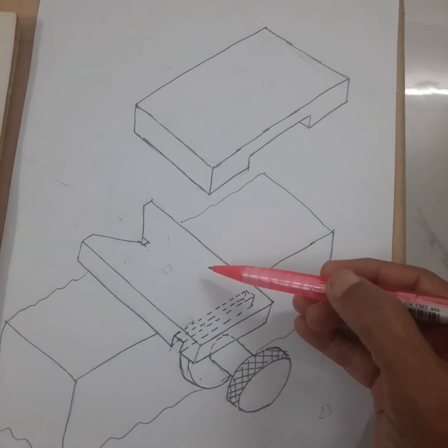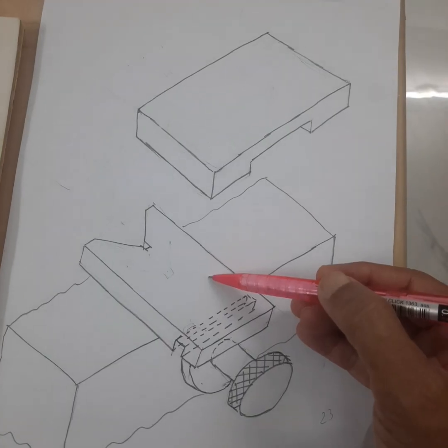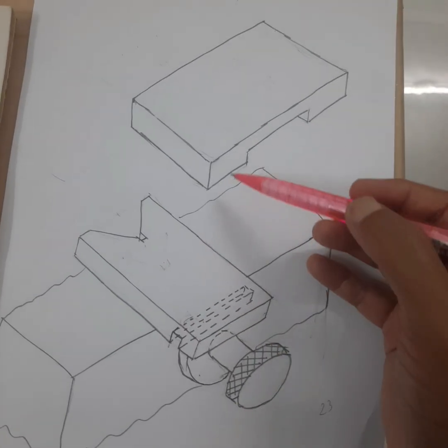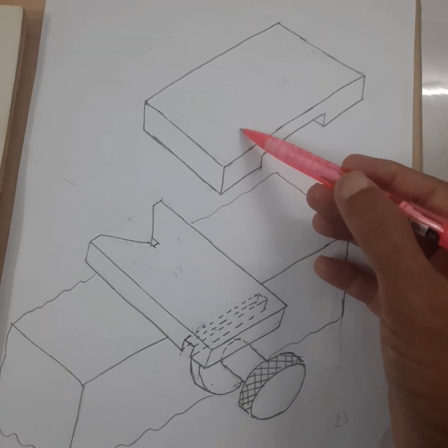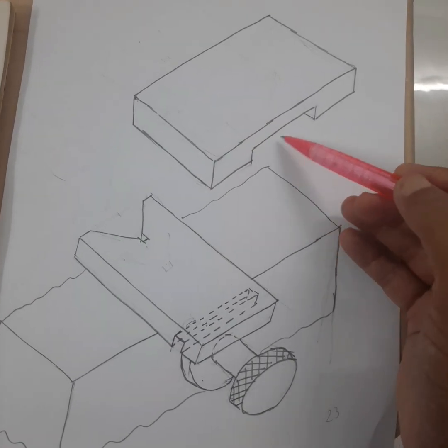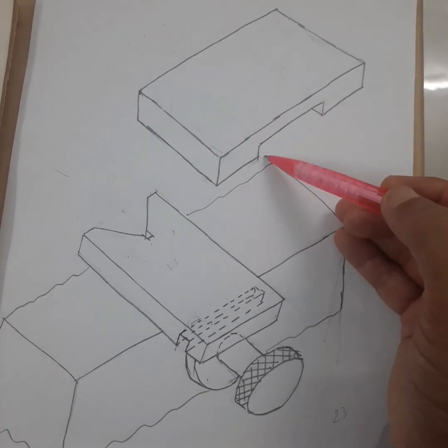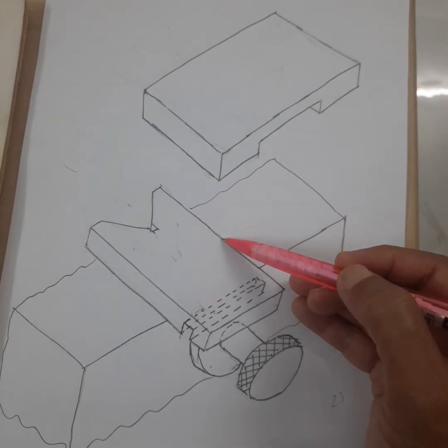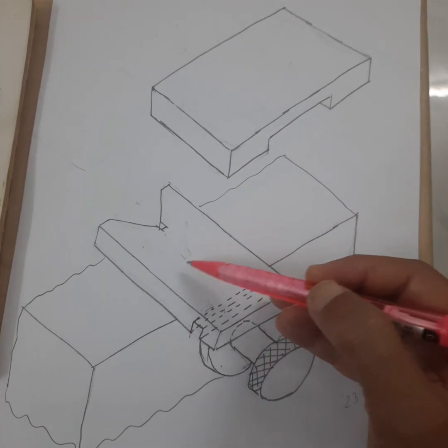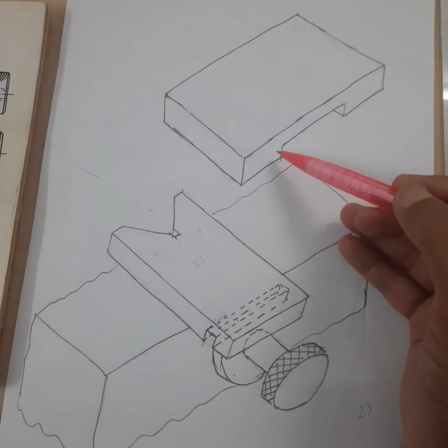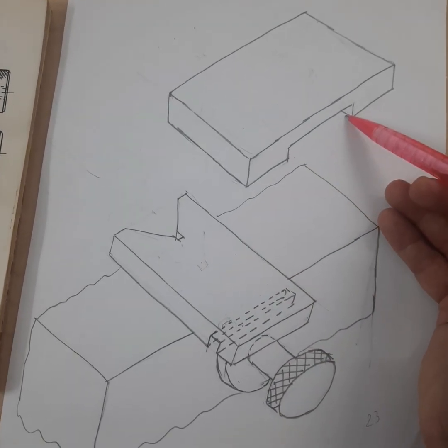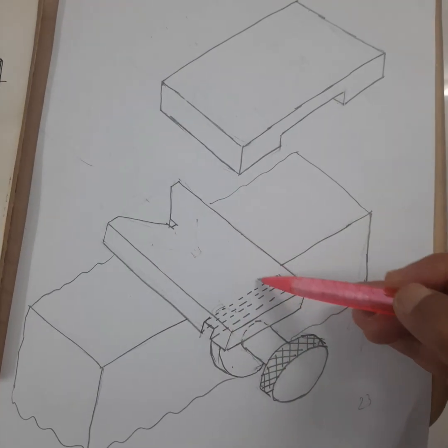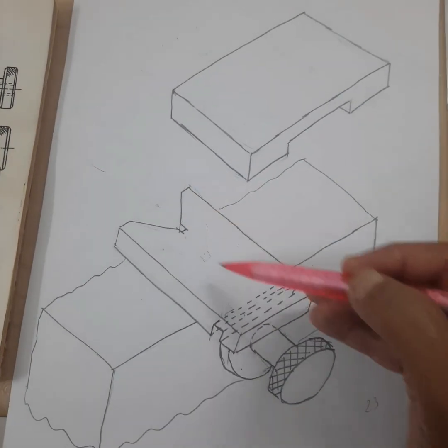This is the sliding V locator. In order to properly guide it while it is moving, we are using a guide plate. The width of the slot on the guide plate corresponds to the width of the sliding V locator. If the width is 30 mm, this should be 30 plus a small clearance. So when you fix it over the base of the fixture, the V locator can be guided while it is moving in and out.